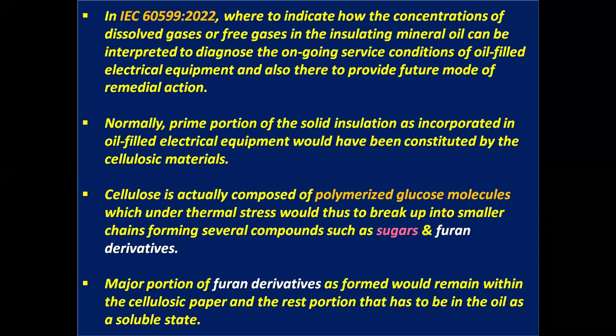In IEC 60599 2022, it is indicated how the concentrations of dissolved gases or free gases in the insulating mineral oil can be interpreted to diagnose the ongoing service conditions of oil-filled electrical equipment, and also to provide the future mode of remedial action.